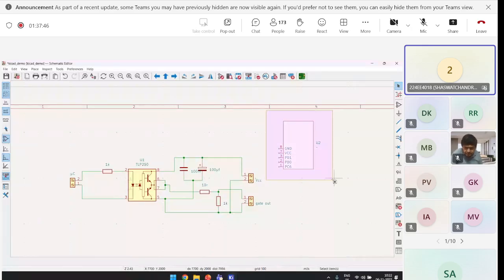After you have created your own symbol, let's say there are 28 pins, right? You will find another microcontroller that also has 28 pins, take the footprint from that microcontroller, and paste it here. Or you can also find the footprint, as most IC manufacturers specify the footprint in their data sheets.